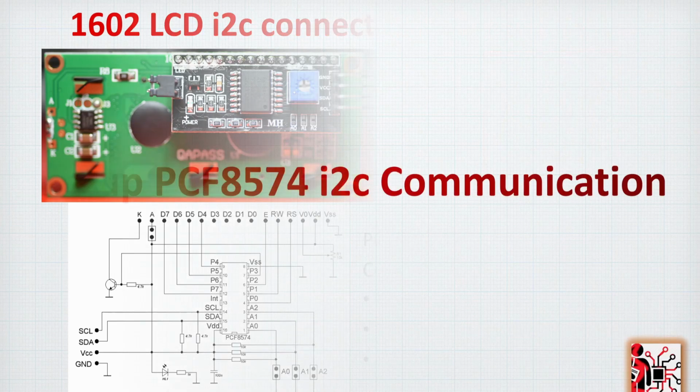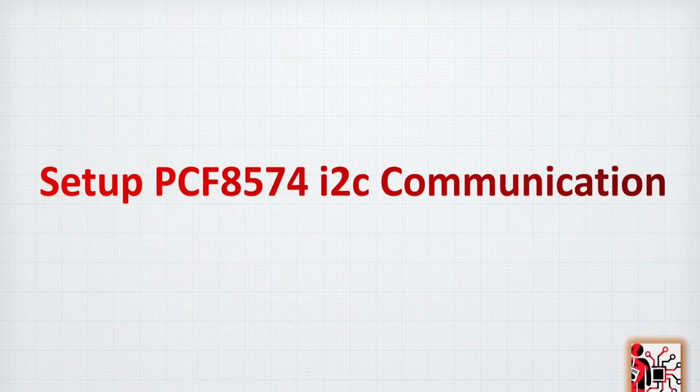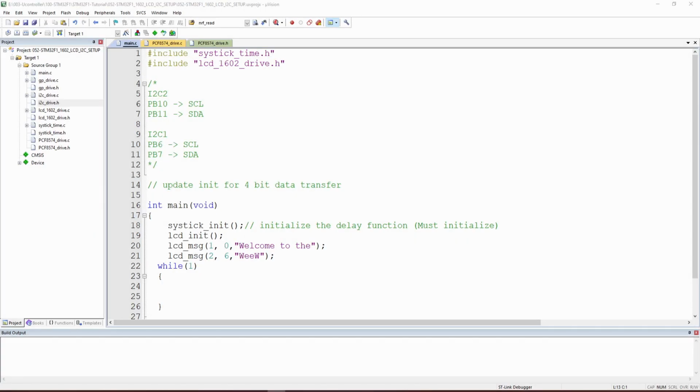So now that we have finished this review, we can jump into setting up the I2C communication for the PCF8574. This is our initial screen, which is exactly the end of the previous tutorial about the 4-bit control for the LCD. However, I'm also adding the I2C driver, for which I added the link to the tutorial in the description.